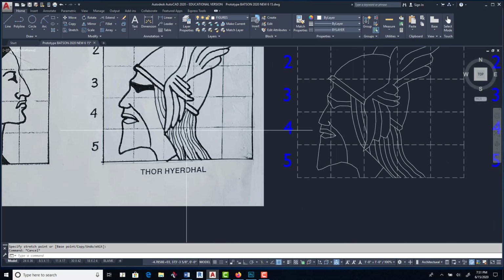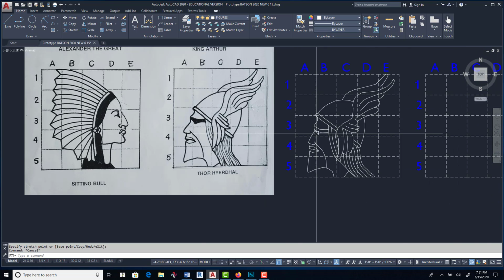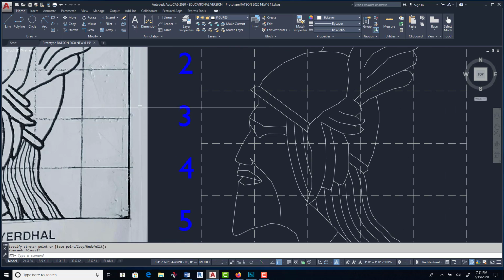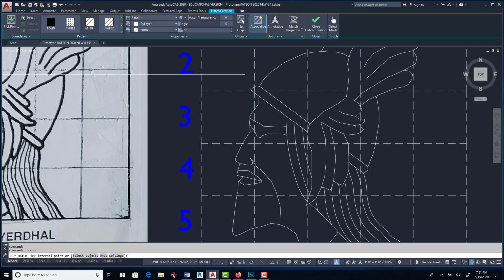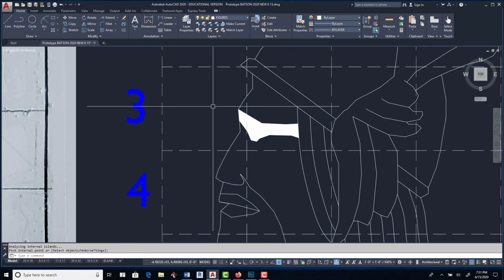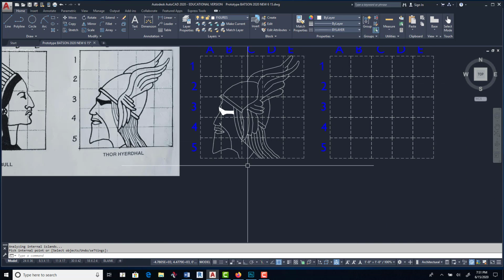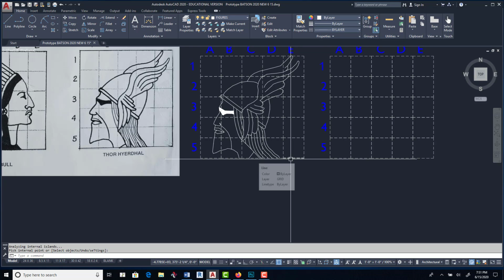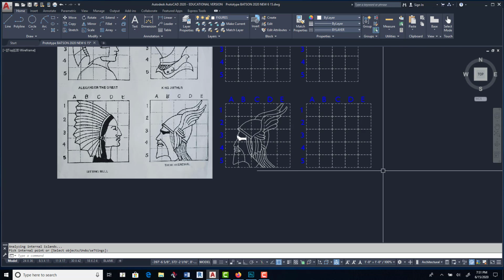Now, there's only one little hatch piece on here. So let's make that hatch. And it's solid, so let's go to the hatch command. There it is up there, hatch, left select. And let's go to click on solid. And let's go to here and to here. So what's white is black and what's black is white. So that's what that is. All right, so now,